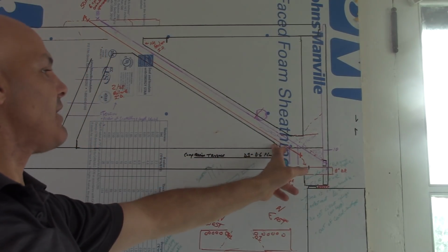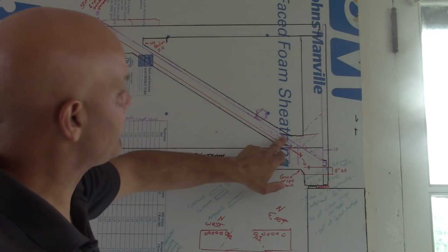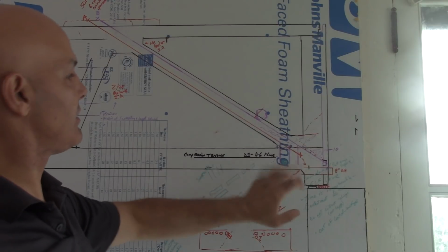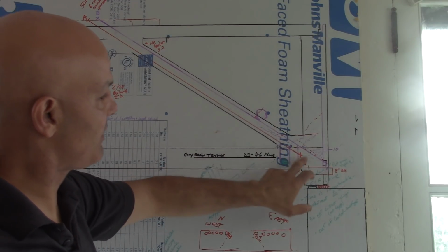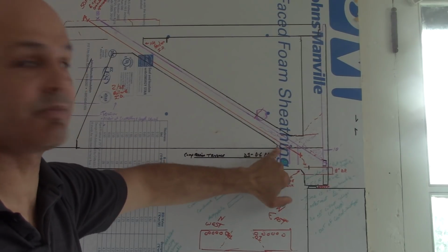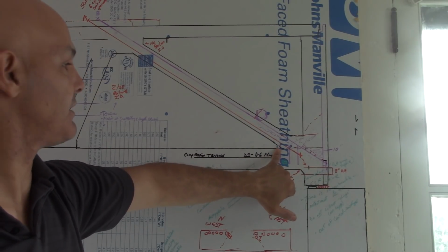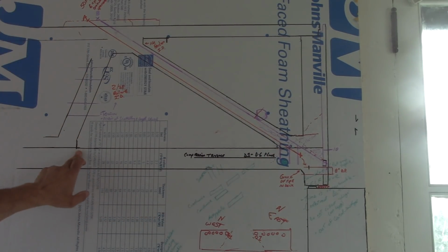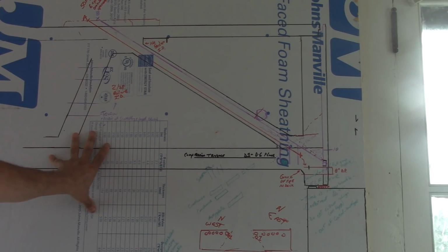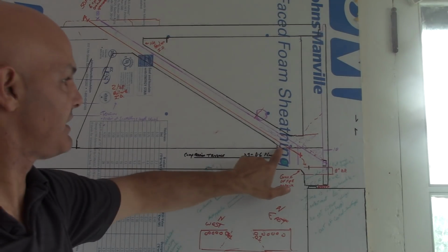But when this dips down, you also want to see possibly this dip up. With this going down, you want to see some reaction here. We'll get to that. But remember, you've got post-tension bars in there at this time, and they're still in tension. These are not detensioned at the time we get to see these cracks here. All you have to do is go down here, and this deck was creeping. It already had creep in it, and it's identified as this.